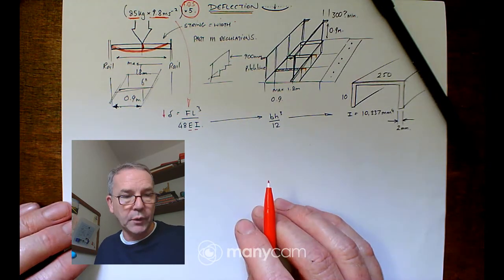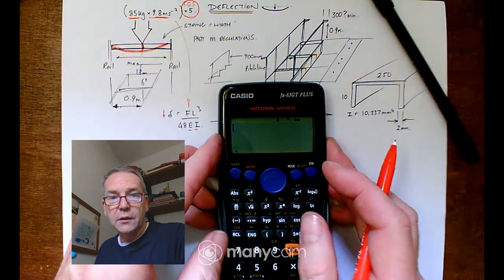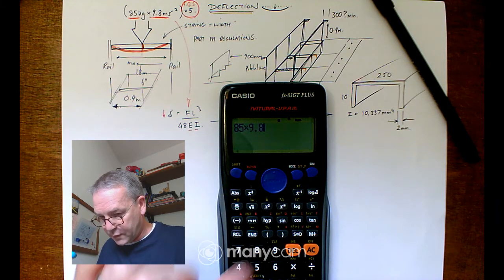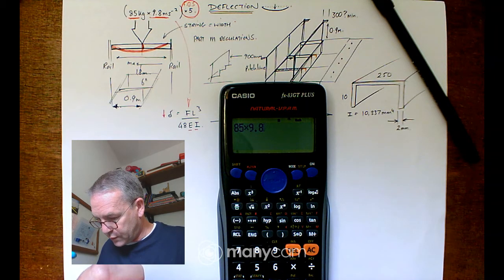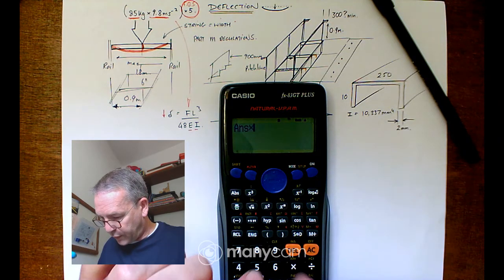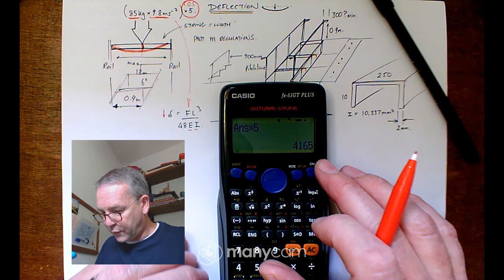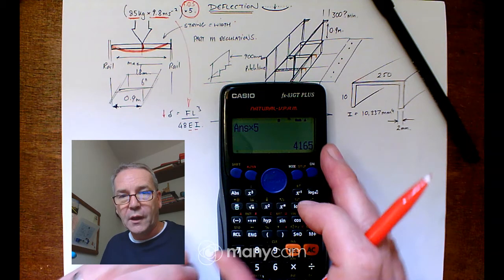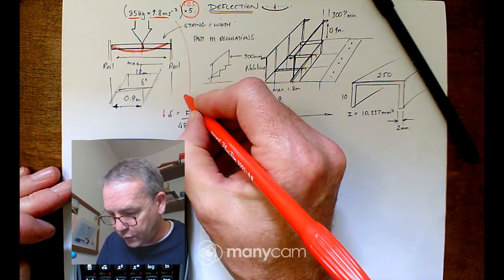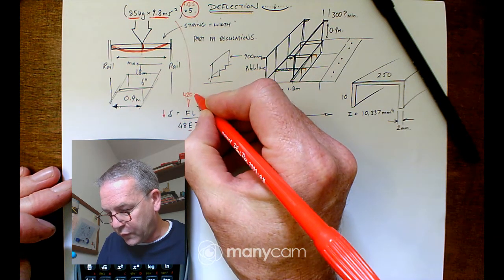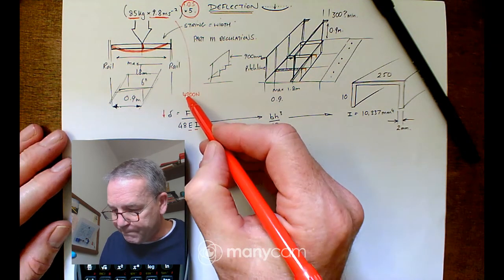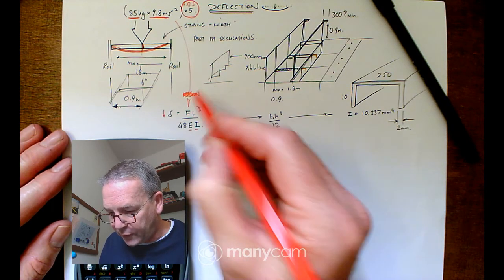So what force would be applied? Put the calculator in. So we've got 85 kilograms at 9.8 meters per second squared. So this would be 833 newtons, multiply that by 5 for the factor of safety. So we need to deal with 4165. So let's go for 4,200 newtons. That's a little bit safer than what we really needed to be. I'm going to go for a round number. So let's go 4,000.